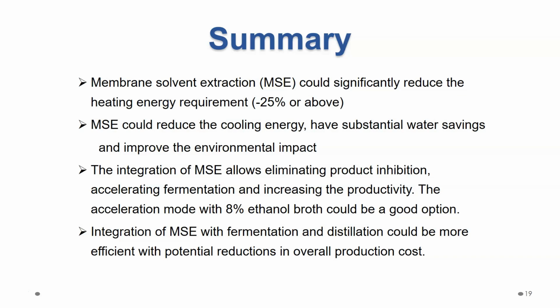In summary, simulation shows that membrane solvent extraction could substantially reduce the heating energy requirement. MSE could have substantial water savings and improve the environmental impact. The integration of MSE allows eliminating product inhibition, accelerating fermentation, and increasing the productivity.